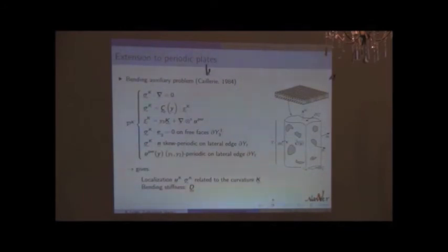If you apply the same machinery we used for the laminated case, formally you end up with the first significant auxiliary problem. It is exactly the same as for the bending of the laminates, but instead of having something you integrate through the thickness, which we did analytically, here you need to solve an auxiliary problem on an RVE.